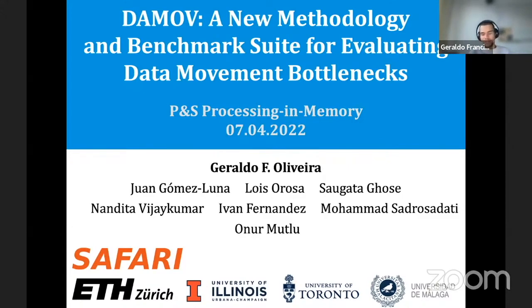And definitely our benchmark suite can be employed to study this. Right now we have a base MESI protocol that comes from ZSim for coherence, and also we have a simple bypass, read-only type of coherence. It's not really coherence, because then you only read from the cache. But yes, we have a pretty naive coherence model for the processing-in-memory cores, and that model could also change to other, fancier coherence models.